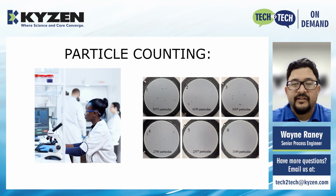So we talked about blacklight inspection, surface energy testing, and gravimetric analysis. The last method of inspection is particle counting. Particle counting is similar to gravimetric analysis. You filter the particles through the filter, and it's placed into equipment where the software inspects and determines the number of particles and their sizes. There are several microscope companies which offer particle counting analysis.